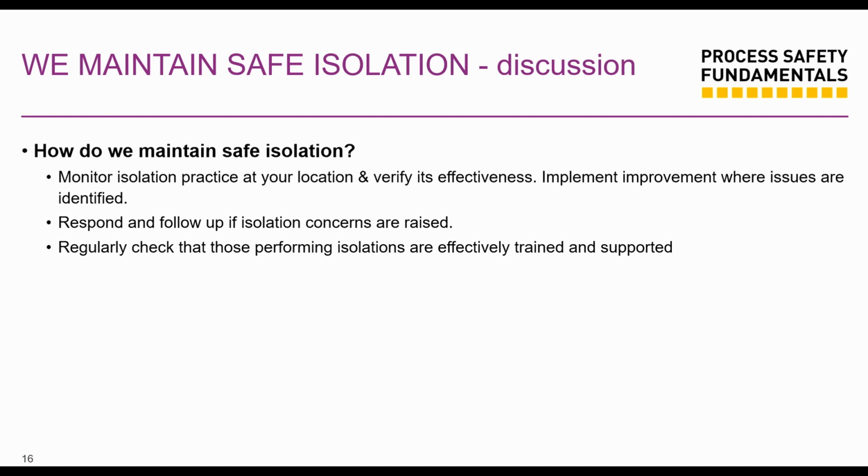Have various isolations in place to make sure that, hey, this is safe. It could be something that's gas. You want to test if it's holding, and then respond and follow up if isolation concerns are raised. If you don't have positive isolation, you should be worried. Regularly check that those performing isolations are effectively trained and supported. We can say this over and over again. Training, assurance, verification, it cannot be underestimated. Thank you so much.